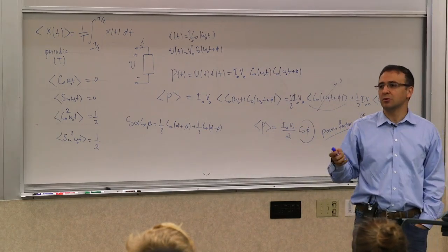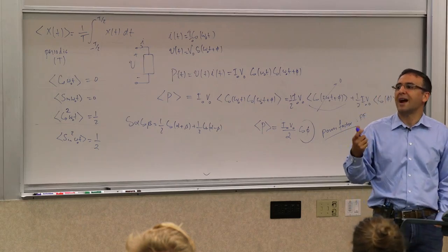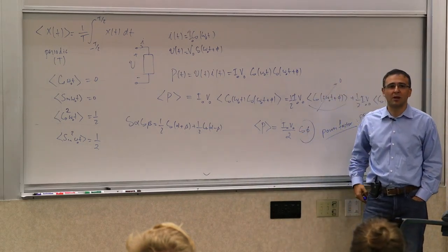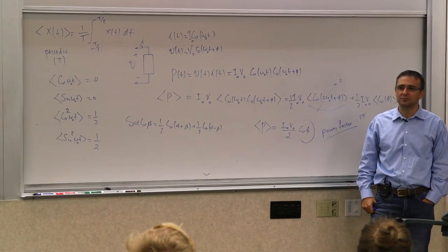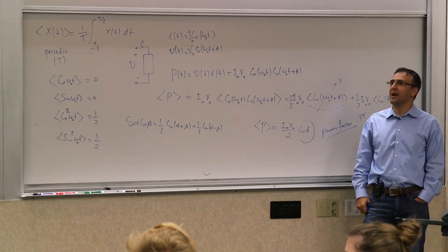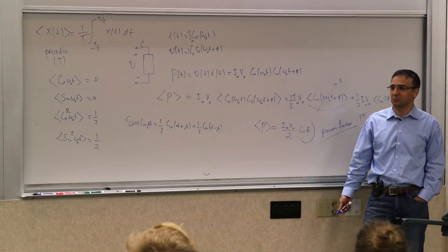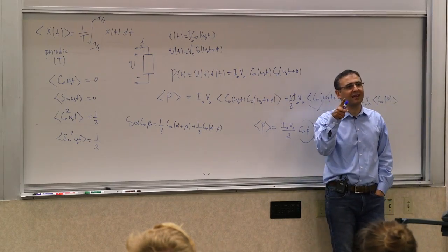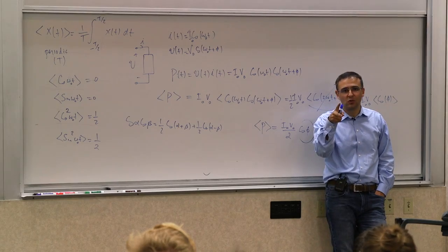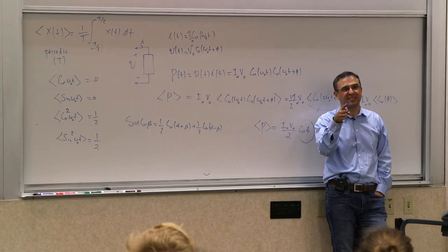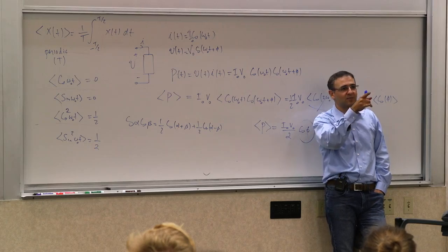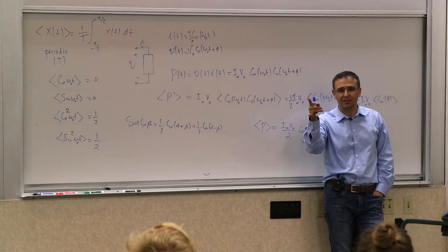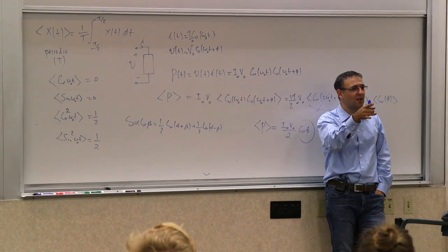Let's say you have a big electric motor and you're trying to make an adjustment so the power factor is proper, or phi becomes small. How can you do that? Yeah. Use a capacitor, right? In parallel, because at that particular frequency, you can make the reactance of the capacitance to be equal. Well, in this case, it would be the susceptance of the capacitance, because it's in parallel. The susceptance of the capacitance to be equal in magnitude, but negative in sign, right, to that of the inductor,